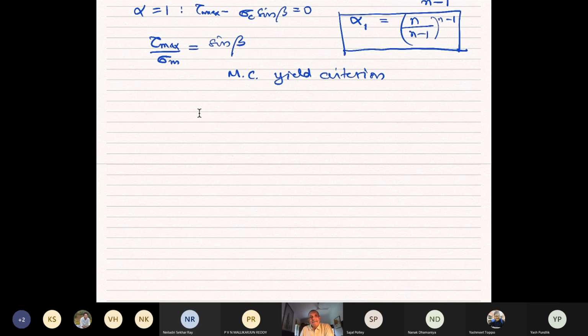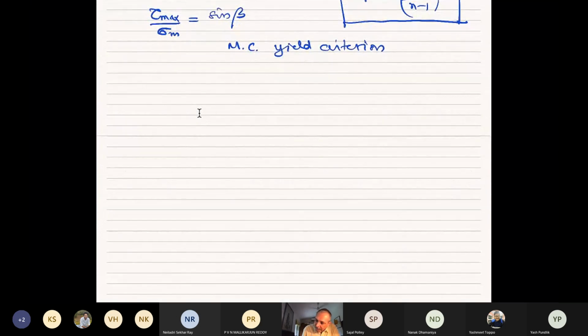So let's just write down the continuity equation for this case, which is the same as before. But there's only one small change, and that is now we don't take density to be a constant. So we get d by dr of rho b into r v r is equal to 0.